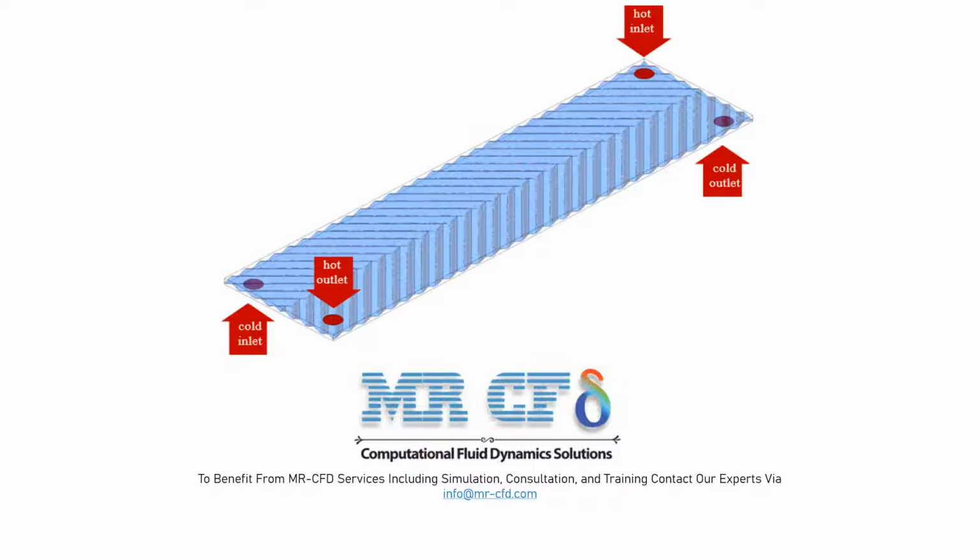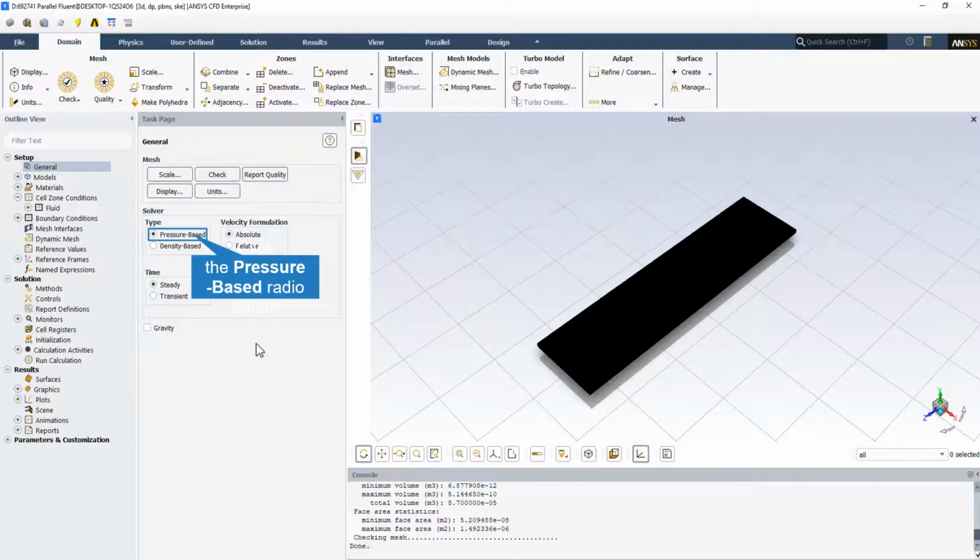The non-conformal structured mesh of the present model is carried out by Ansys meshing software, and the element number is almost equal to 640,000. Several assumptions are considered for the present simulation. The simulation is a steady state, the solver is pressure-based, and the gravity effect is ignored.